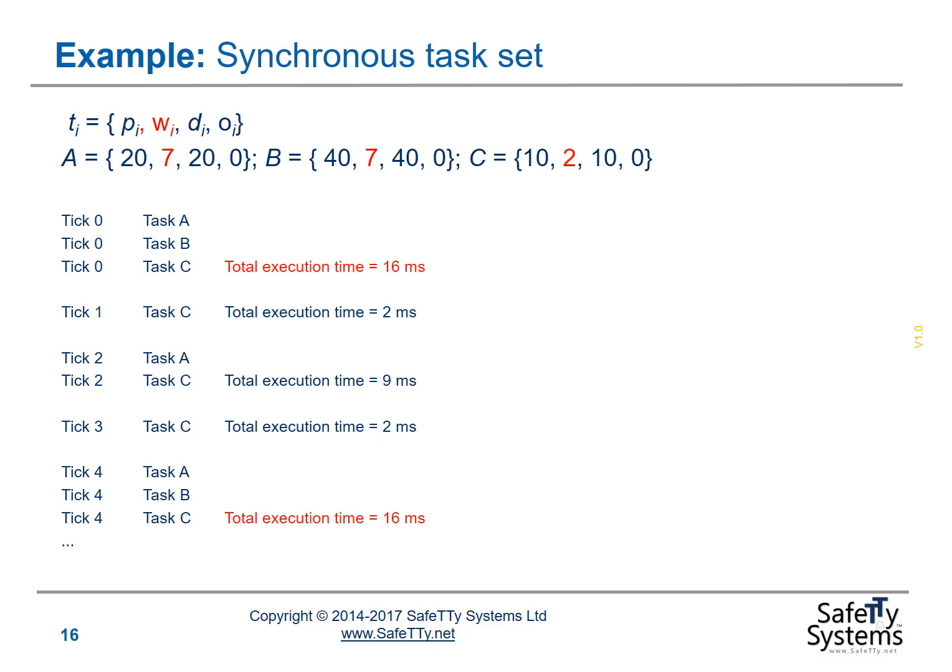What that means is, at best, that task C, in this case, for example, which follows in the next tick interval, will have a very high level of jitter. Now we worked out the average CPU load to be 72.5%, so we know that we can schedule this task set, but we may be concerned about the level of jitter in task C, and we may not want to run our task set in this way. What can we do?